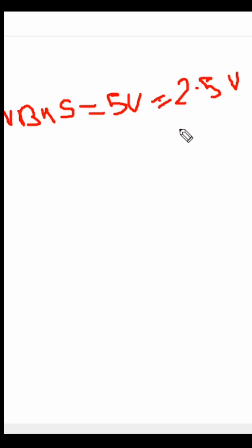Sometimes you can see even some little current consumption on your multimeter. You just see that you have some little number, not up to 5 volts. So you see on the test point of Vbus this thing appearing. It's telling you that the voltage is not enough. Okay, all right, that's the first case that usually happens to this guy.